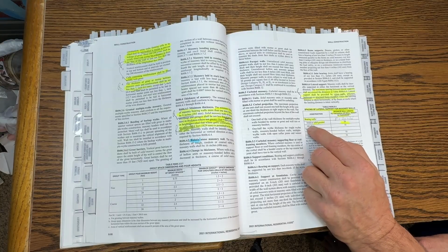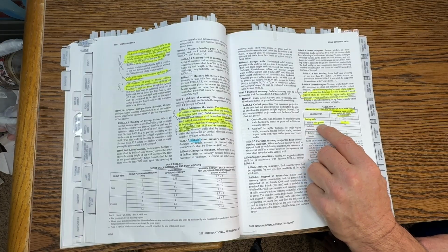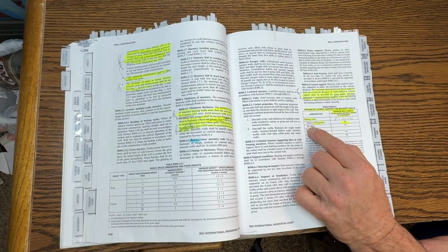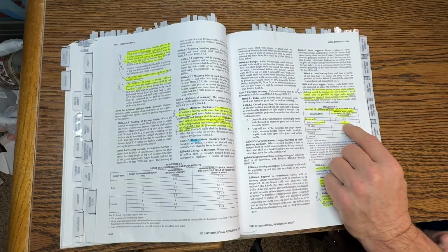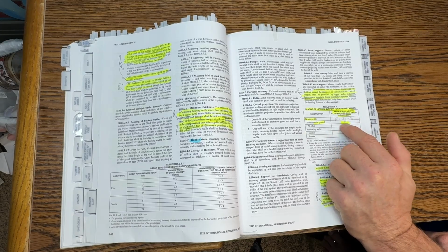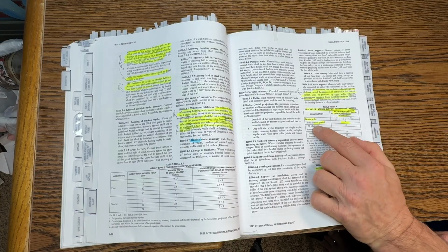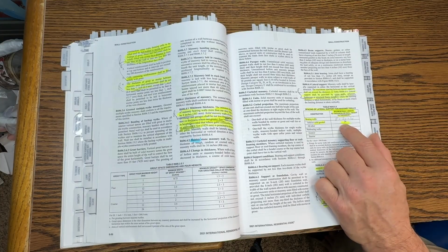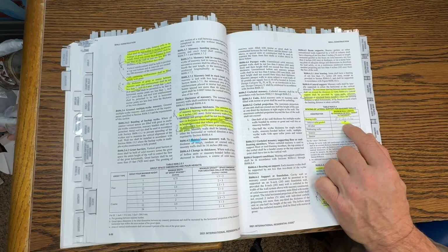So the solid or solid grouted, that's what we're talking about in problem 124. It's a bearing wall. And the question is, you don't have a support on this. And this is wall length, not wall height, wall length. And if you have 8-inch thick, in this case, based on this, you can have 20 times 8 or 160 inches without lateral support on that wall. So the answer here is 160 inches.